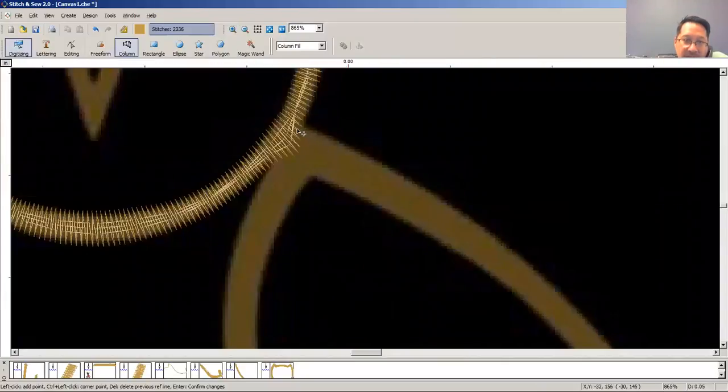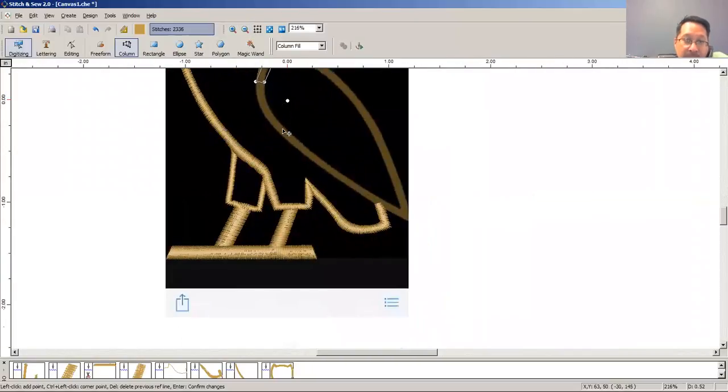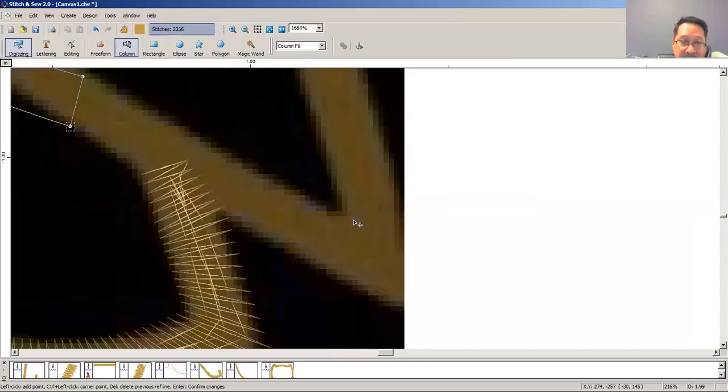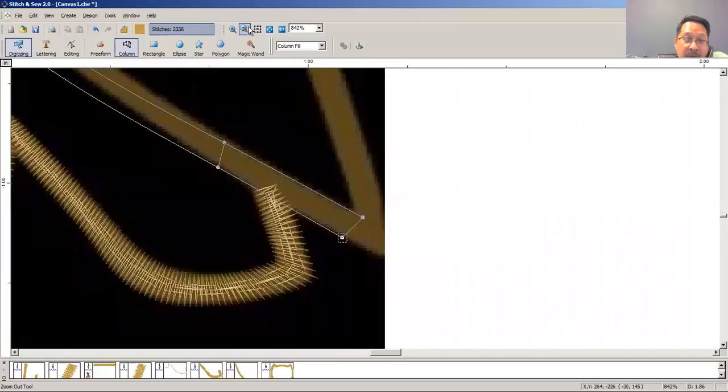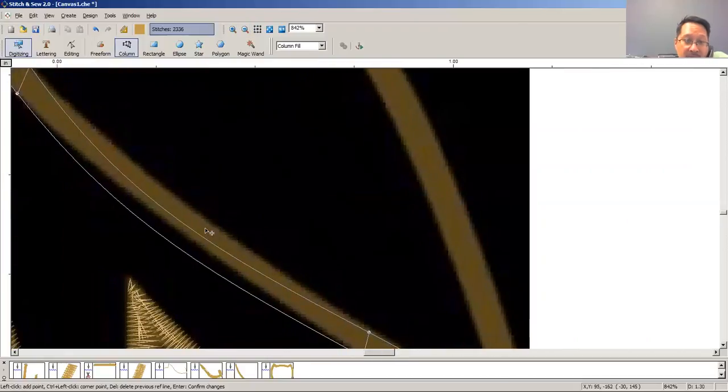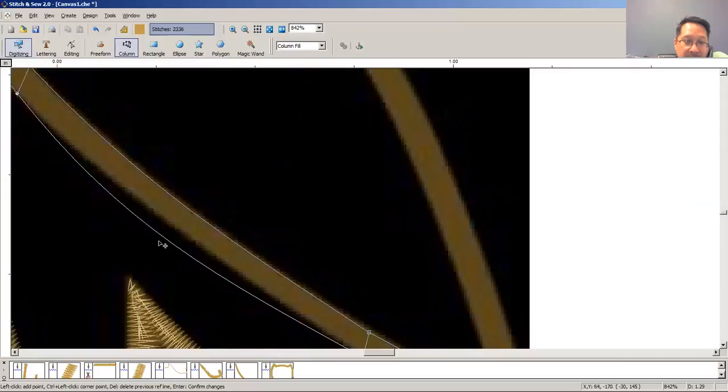Okay. Right. I'll go and finish this out by creating what's called a capped corner, because I think the bottom of the wing here is going to be severe enough that I have to do a capped corner, which is a 3-part corner. We're not mitering 2 pieces into each side. We're actually going to wind up tapering into a 3rd triangle that's a little bit on the wide side, but it winds up working pretty nicely.